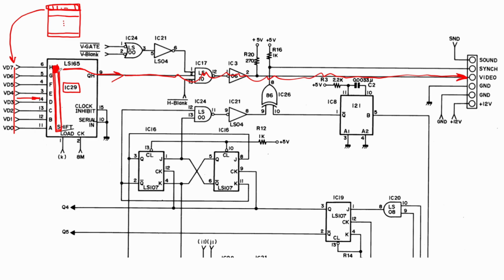Now, after it has shown the first bit, and before the next byte comes in, what it will do is shift everybody one position up in this case. So what was the first bit now falls out, and what was the second bit now goes to the position of the first bit, and that then gets displayed on the screen. Next cycle, what was the third bit will make its way to this position, and then it's displayed on the screen, and so on and so forth until all 8 bits of this byte have been displayed on the screen, and that will correspond to one little line of 8 bits.